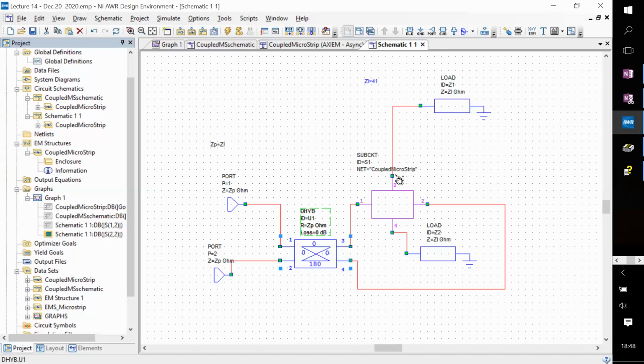That is again important, because a 4-port device, so this hybrid coupler, could also just be something like a coupled microstrip line. It could be, it's not, but it could be. But you always want the ports to which you are connecting signals from outside to be always a 50 ohm reference.